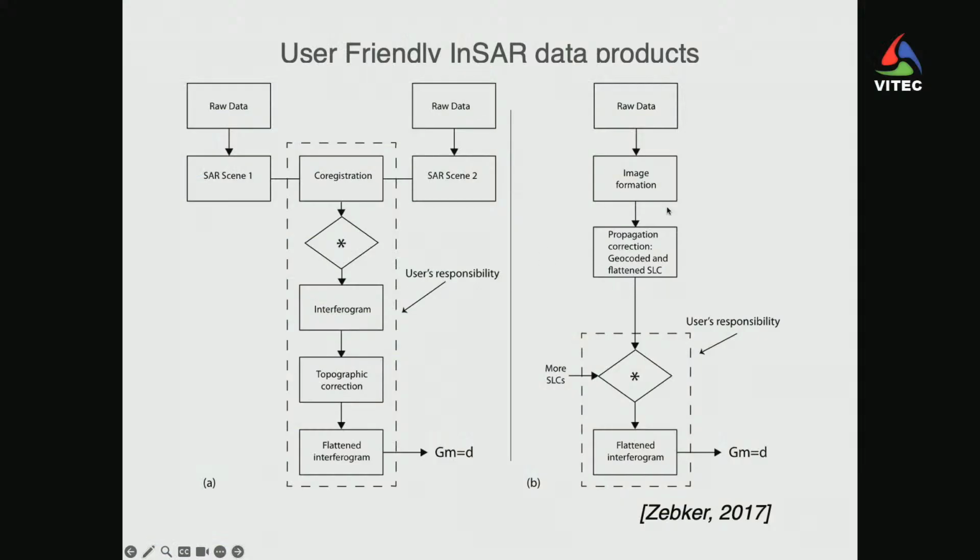We figure out how to form radar images directly in a lat-long grid, which reduces the need to later register them, resampling them multiple times at multiple locations. And once we have this geocoded SLC image, another important step is, instead of trying to do those topographic corrections later on after you form the interferogram, we figure out how to add a phase term into these radar images during the SLC stage. Not me, it's other people, like my PhD advisor, I work with him more closely.